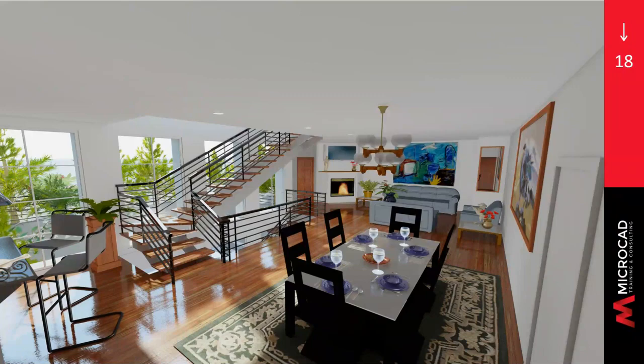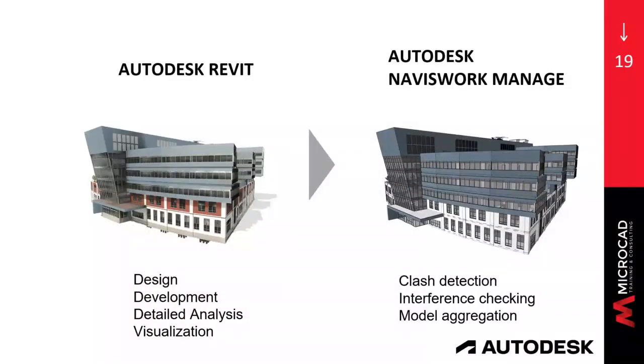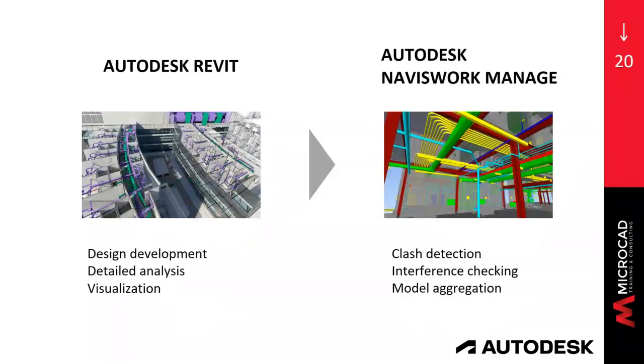Furthermore, next tool, let me talk about Navisworks. Navisworks Manage is going to be the tool that unifies all the industries. So within your own design, you will be able to do clash detection and interference checking. But furthermore, you can combine all the Revit files throughout all the Revit disciplines and start doing the important clash detection, from my point of view, which is the clash detection that you need to perform before going onto the site